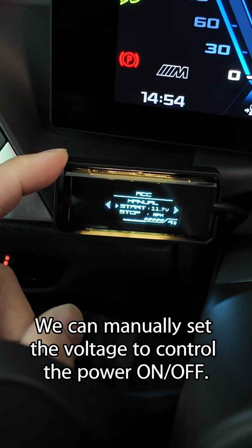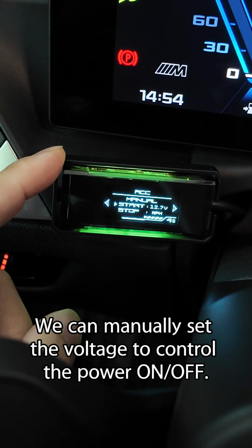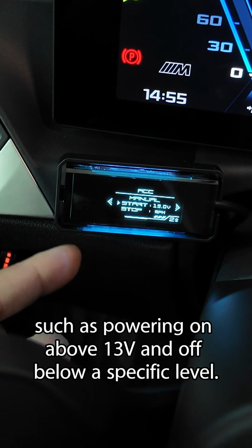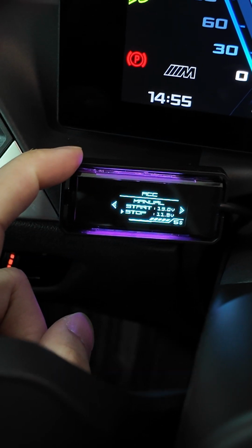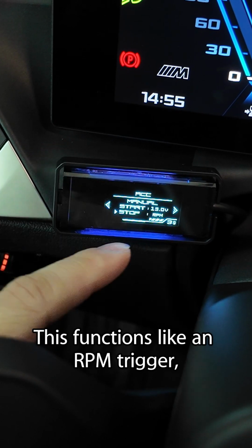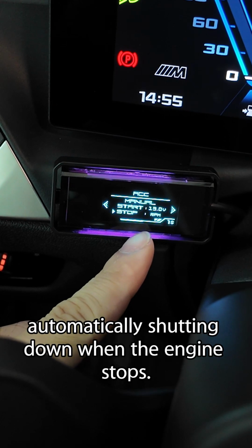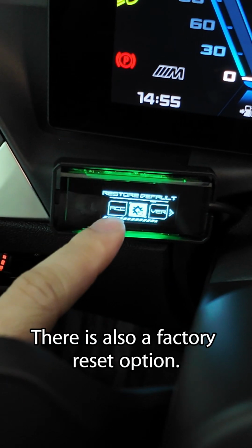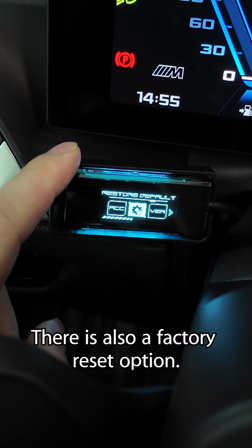We can manually set the voltage to control power on and off, such as powering on above 13 volts and off below a specific level. This functions like an RPM trigger, automatically shutting down when the engine stops. There is also a factory reset option.